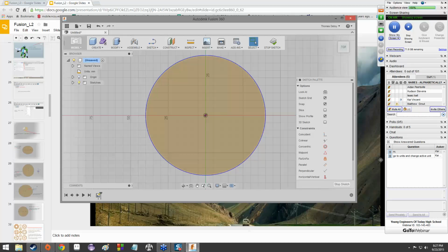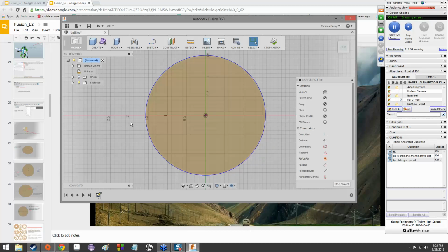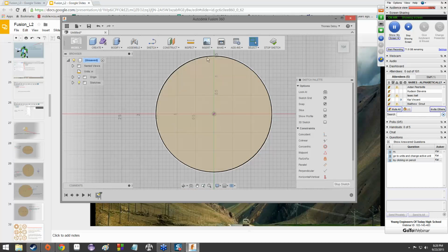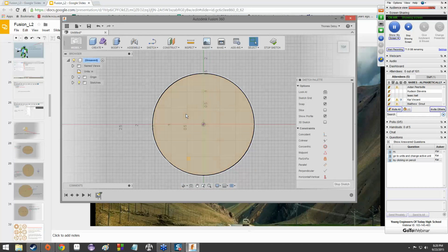Yeah, exactly, Kai. Exactly. We're going to go over to your units on the left-hand side, and there's this Change Active Units button which appears. Yeah, precisely. With the pencil and the paper and the ruler. Exactly. And then that's labeled Change Active Units. So we got the unit type here. Click on that. Change it to inches. And then hit OK. So now we've got a circle of some diameter. We're not really sure because it's kind of hard to tell now, but it looks like it's a little bit over 3 inches.